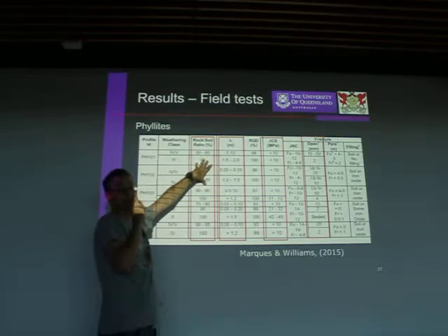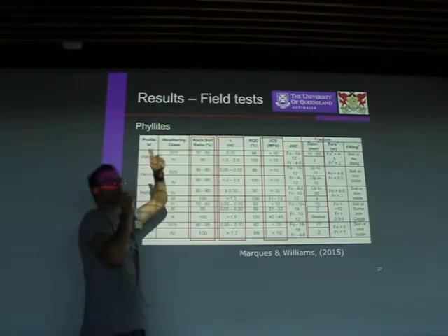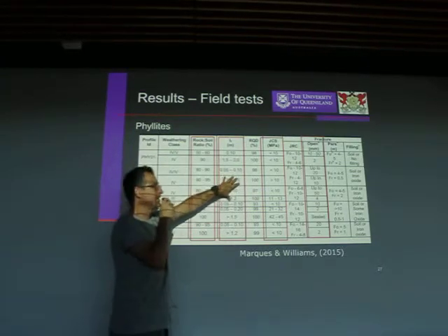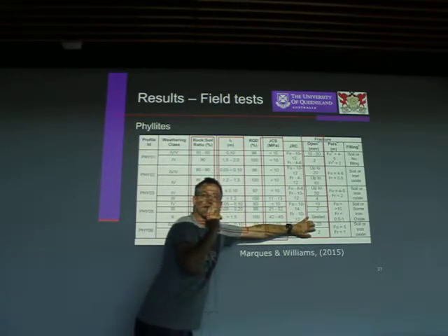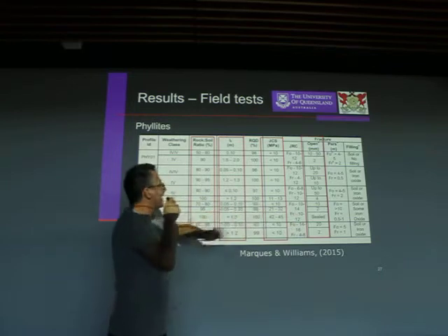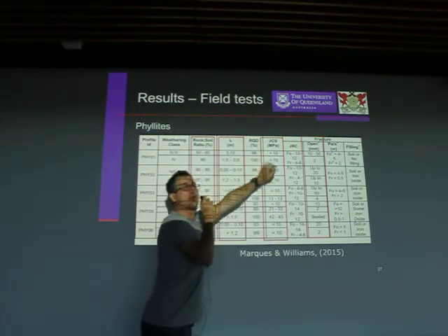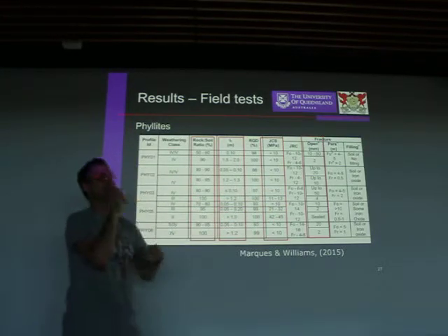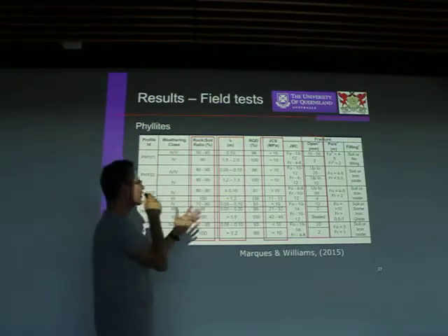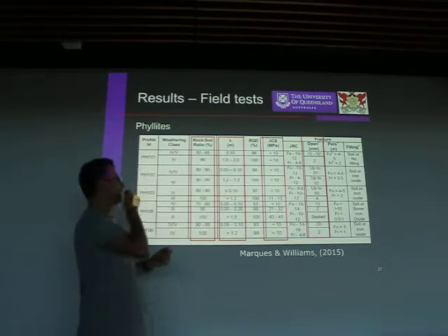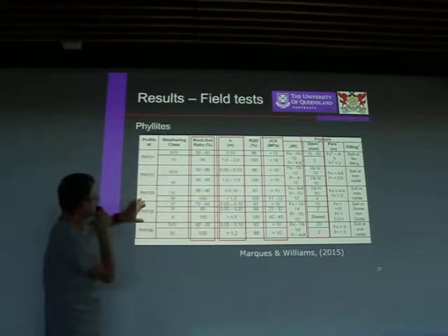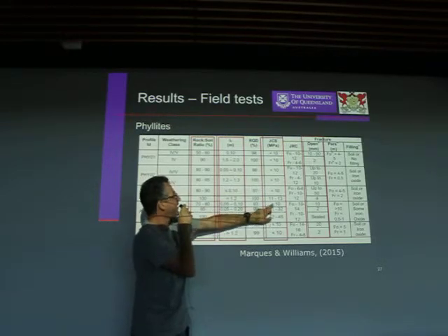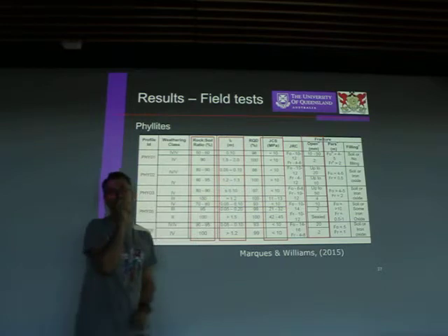Mainly rock to soil ratio, which used to be a parameter used by beginners in the study of weathering profiles. The fracture index as well, the openness or aperture of the rock fracture, and surprisingly also the joint coefficient of strength. The problem here with this joint coefficient of strength is that I have used a Schmidt hammer, an N-type Schmidt hammer. That's not very good for weaker materials. But even so, if I take a closer look at this Phyllite 05 here, I can see that the JCS is able to identify the different layers that I have observed in the field.